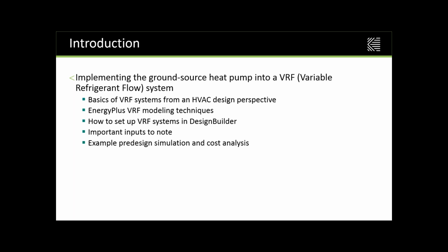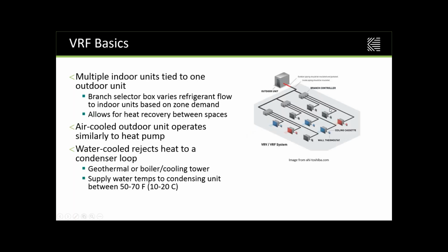I'm going to show some of the techniques that EnergyPlus uses to model the energy consumption, how to set them up using DesignBuilder, a few important model inputs to note and how they will affect your simulation results. And then at the end, I'll go through a case study where we presented a customer with 4 different HVAC alternatives and showed how much savings could be generated from the VRF system using DesignBuilder.